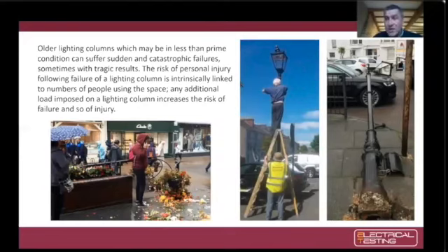the root section, cleaning back the root, cleaning away the weld area and the lower plate, and then structurally testing with ultrasonic devices. It wasn't possible to test the column from above ground level, so it was a significant commitment to identify whether these columns had below ground defects. And only once, when the defects were either identified or not found, was then the column passed or approved.